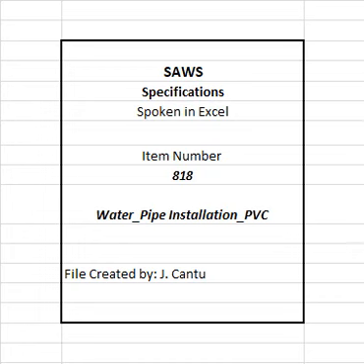C. Submit written verification that the pipe manufacturer has been manufacturing pipe per required ASTM with similar design, pressure and size as this project. D. Submit written verification from the pipe manufacturer demonstrating compliance with the production and delivery schedule of the pipe as indicated in the contractor's schedule. 2. Contractor shall submit manufacturer's product data, installation recommendations, shop drawings, and certifications.